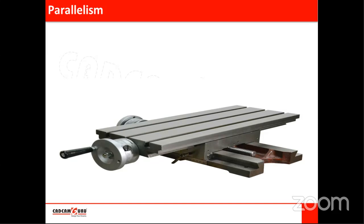Okay, so in a number of machines you can find parallel surfaces, and we are expecting parallelism between these two surfaces, meaning the surfaces should be from the same component. You can find it in a lathe machine also. In the lathe machine bed, there are two surfaces, and they should be parallel. Okay, slide surfaces, slide ways.